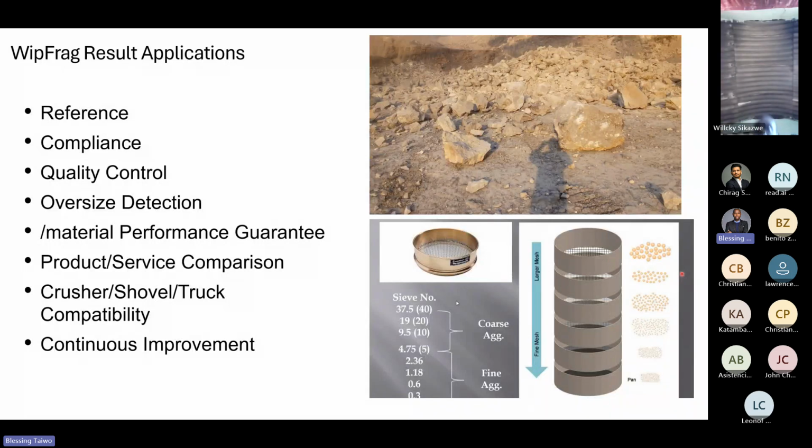So here, image analysis technologies are technologies that allow you to carry out virtual sieve analysis. Just like sieving, where you take the material to the lab to pass through screen sizes, in this case you are taking the picture of the material and assessing the material through virtual sieve. The picture of the material you captured is like you taking all that material in the picture and running it through sieves.